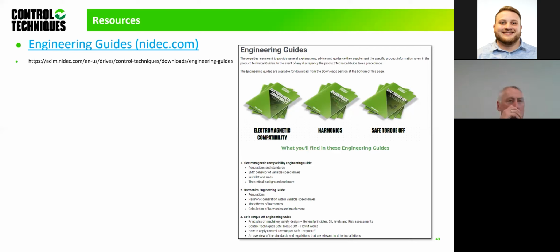The point of common coupling, maybe for a high-rise building where they have HVAC drives and all that, is most likely going to be LV, because you're interacting with different departments on that same power supply. But again, what happens if you're a big industrial unit making steel or paper? Your PCC internally may be important for you, because you're the only person on that low voltage. But if you're interfering with a local community or another customer, another industry or another factory, then the point of common coupling may, well, most likely be MV.